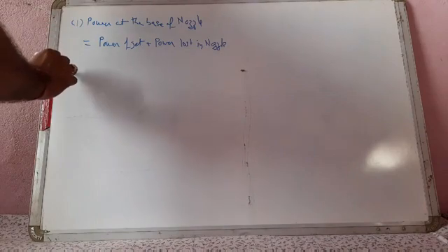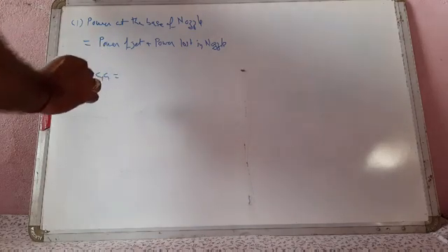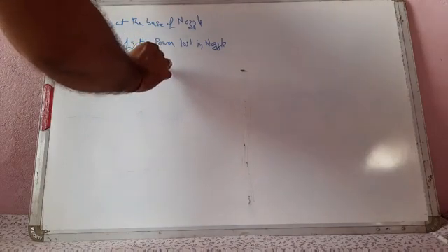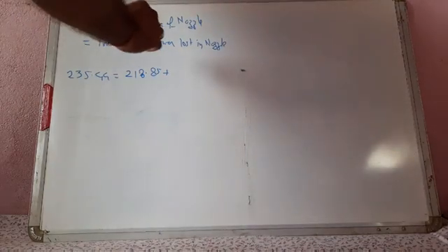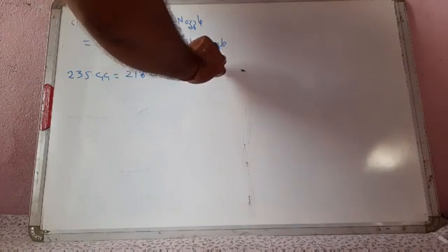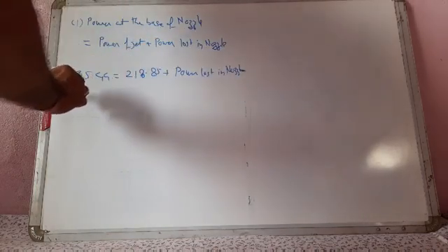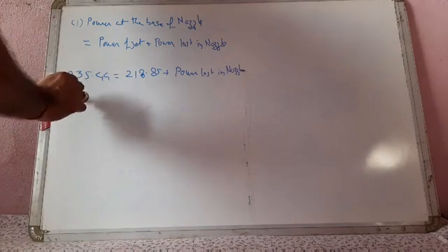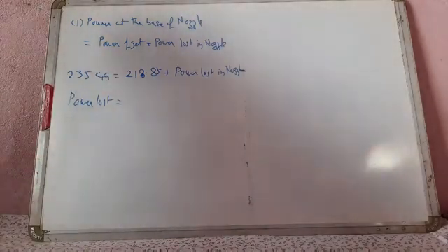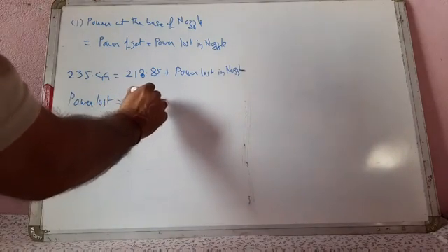So here 235.44 equal to 218.85 plus power lost in nozzle. So the power loss comes 16.59 kilowatt.